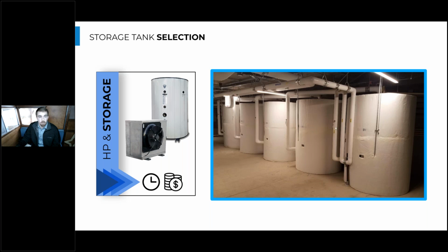So thinking a little bit more about storage tanks, we talked about how it's really important how they're paired with these heat pump water heater systems, and it's really important how they're plumbed up. So we need to think critically about the storage we're selecting. And from a high level, it's okay to see a lot higher volume of storage, and actually preferred to see a lot higher volume of storage in a heat pump water heater system than you would with the equivalent boiler system, because these heat pump water heaters have a lower recovery on average, so they rely on the storage to cover the peak loads from the building.